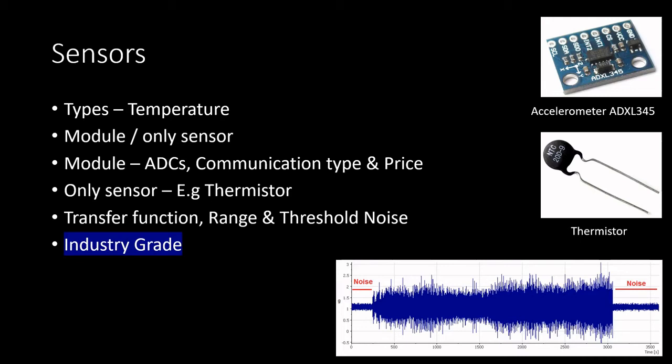So it will not be good for you to use that sensor, because at low acceleration, random noise will be collected in your data and that will be difficult to analyze. And if your signal to noise ratio is in that range and noise is low compared to the signal you have, then obviously you can go for the cheaper sensors also.